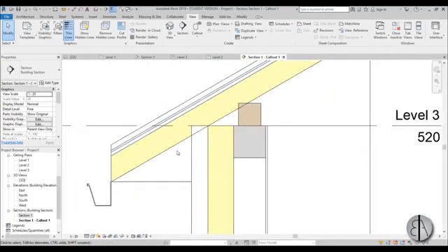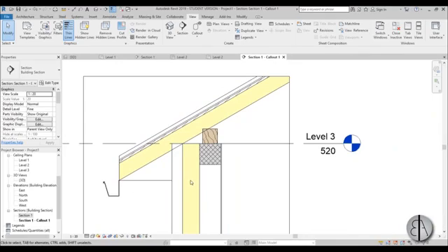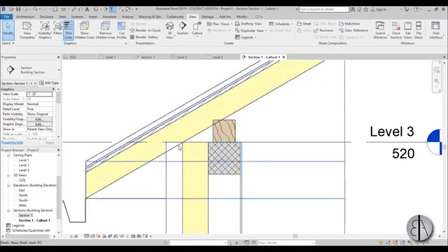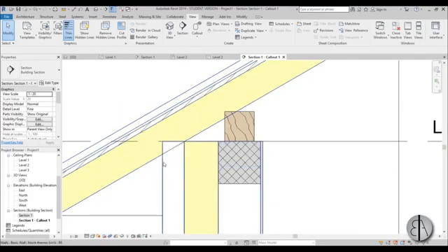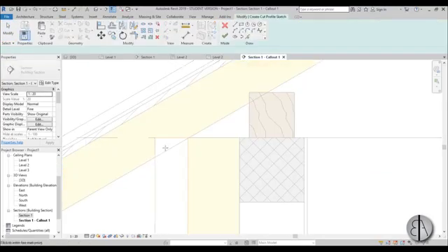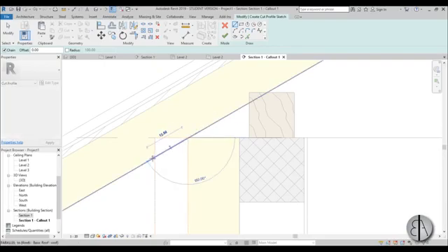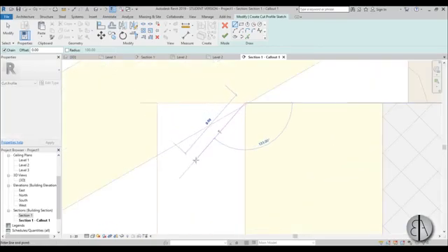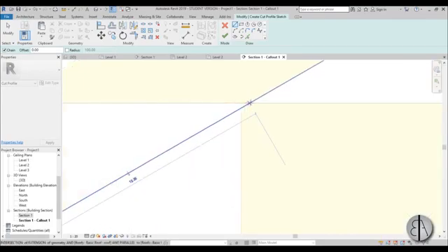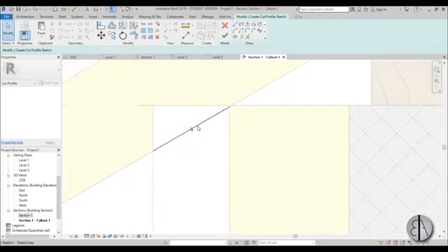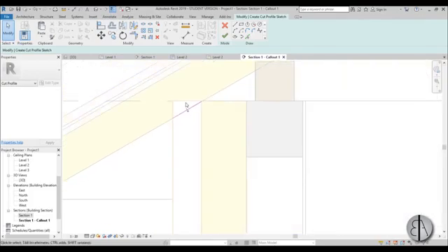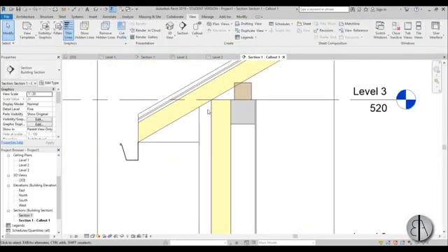So now we need to fix this up over here. Usually you don't want to have insulation going all the way out, you want it to finish kind of over here, so it's transferring from the wall all the way into the roof. So how do you do that? First, let's cut this angle off over here because we don't need that one. So you just go again into view, cut profile, select this thing, you create one line like so, make sure it's going like this. Yeah, zoom in and make sure that this little arrow is pointing inward, and you just go finish. Yeah, that looks right.